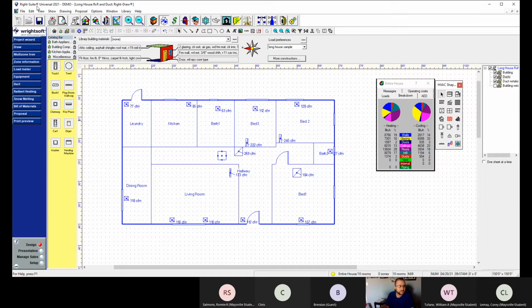But since I can't get it to right away, I'll have to come back to that. But anyway, when you draw this out, basically what total equivalent length is saying is: I've got this many feet of trunk, this many feet of run to get to that, and this many bends or this many types of takeoffs or boots or elbows or whatever.